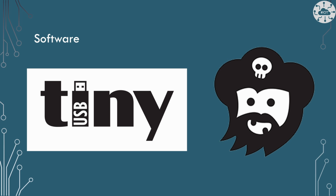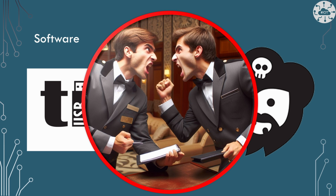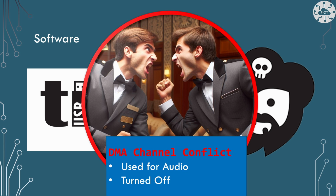This really should be as simple as using the TinyUSB library and the PIMORONI Pico library and bringing those two together to allow us to take animated images from the USB drive and write them onto the Cosmic Unicorn. But of course it isn't that simple, because these two libraries fight, and they fight because there's a DMA channel conflict between the two.